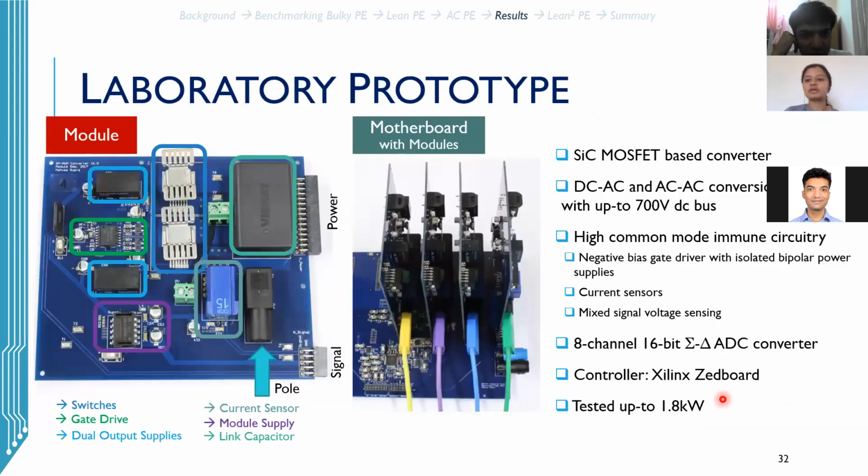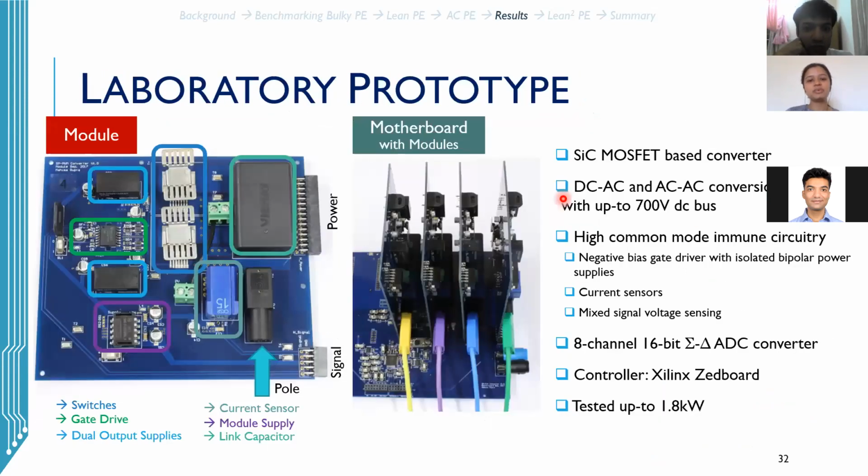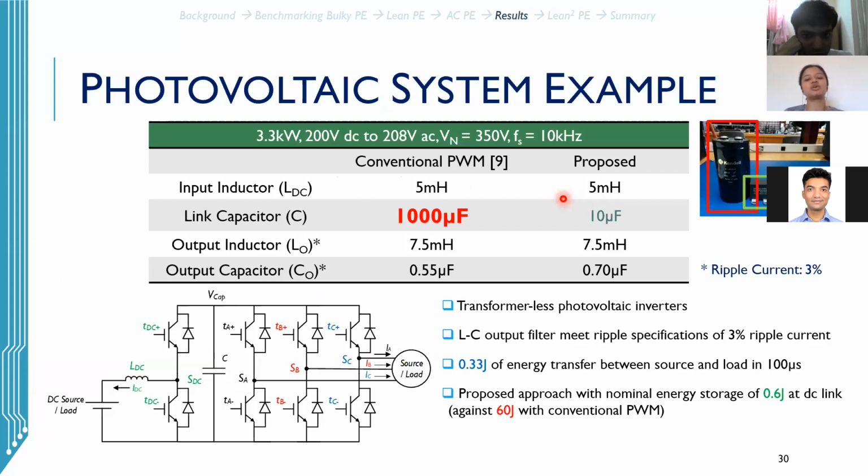And what was the switching frequency in this case? In this case, we limited it to 10 kilohertz. Okay, but is it relevant to switching frequency, or does it depend on switching frequency? But I think power converters, you operate less than 50 kilohertz, right? So can we go like 10 to 50? Yes, we can do that. The prototype that we developed, we operated up to 50 kilohertz. We can definitely use that approach, but we used 10 kilohertz operation.